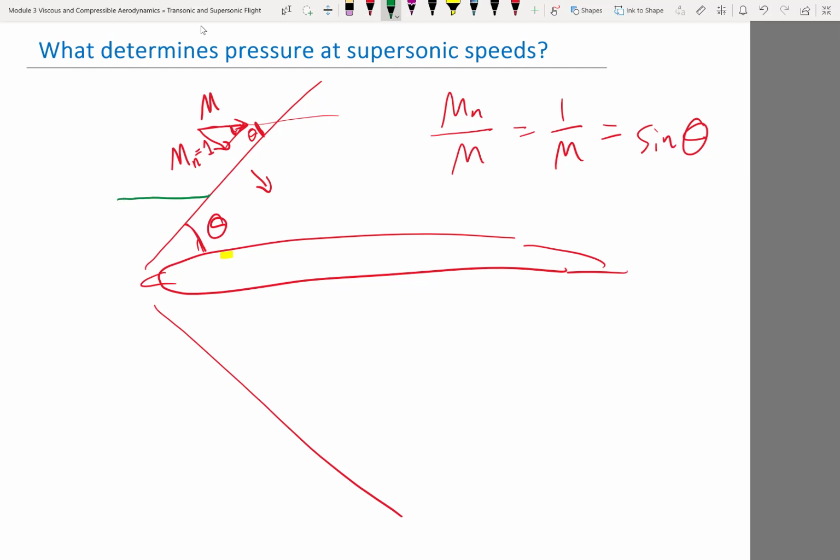As we said, the tangential velocity would not change when you are crossing a shock wave, but the normal velocity does change. Would the normal velocity increase or decrease after you pass a shock wave? Decrease, right? Now the normal velocity decreased while tangential velocity does not change. The flow direction would turn in which direction? Would turn up, exactly. Would turn up.